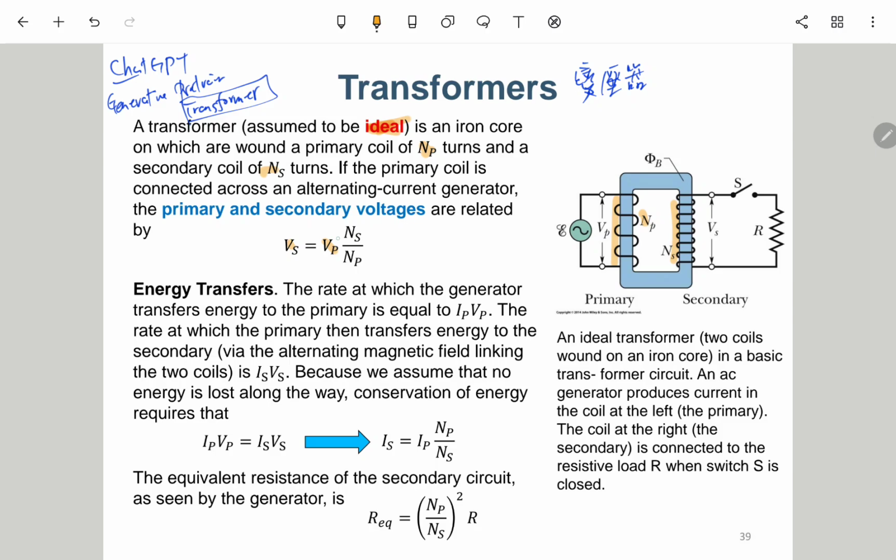Okay, it is actually proportional to NS, and yeah. So I mean the secondary RMS voltage. Okay, so actually if you use RMS voltage for both, you apply for both the primary and secondary. If you use amplitude, it is still correct. You just make it consistent.